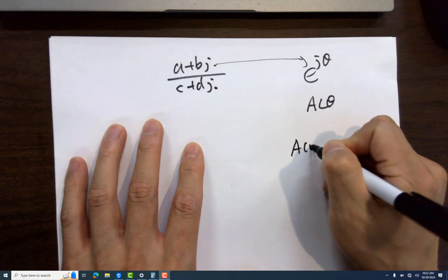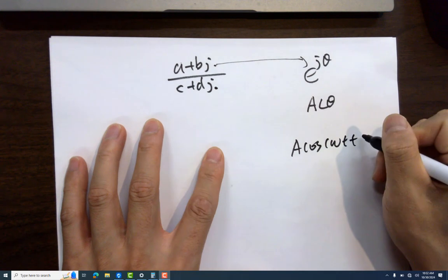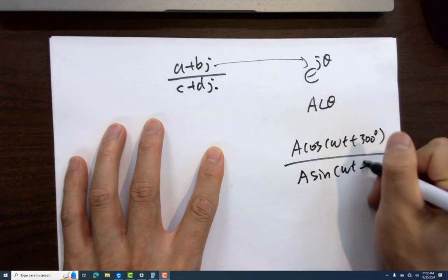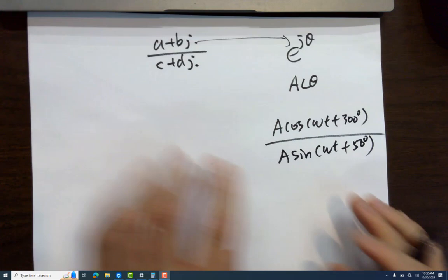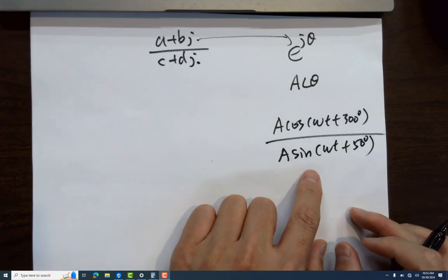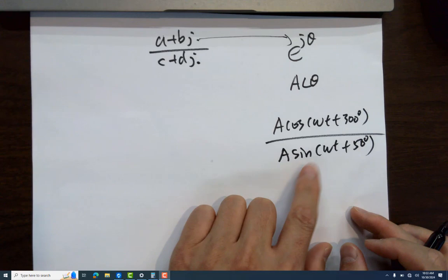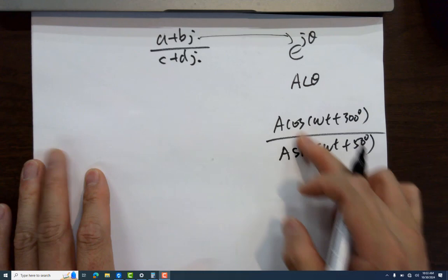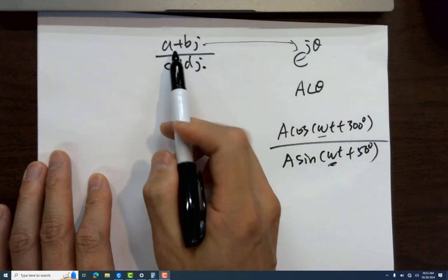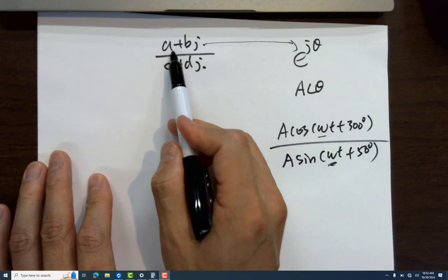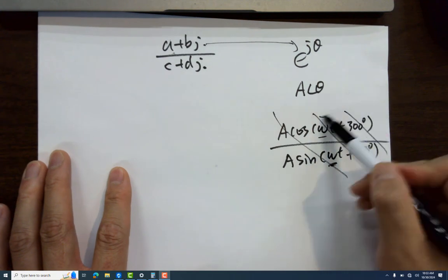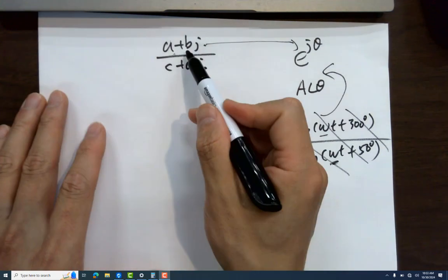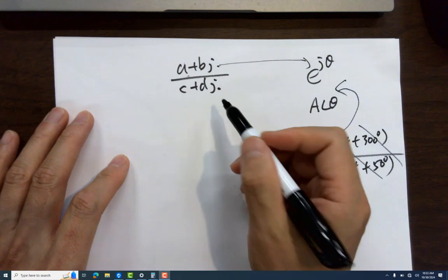If you do this, who can tell me how to do it? It's very difficult. Okay? When you put the time in there, it's difficult to do the calculation. However, since we have the same frequency, we only worry about the phase and amplitude. So we don't want to do it in time domain. That's why I convert it to the phasor, to the rotating bar. So they are all rotating bars. It's easier to calculate. So now let's see how I do the division.